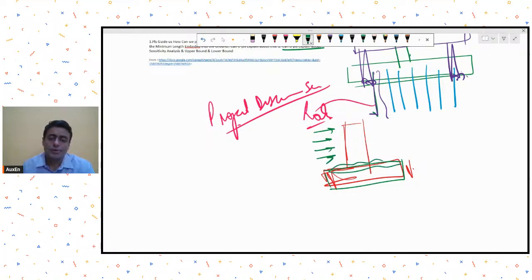So you basically want to see the podiums at two levels of stiffness. When I say podium, I also mean to add any existing basement walls and other podium slabs. Any system which is taking the lateral load due to wind and earthquake acting on this tall building and transferring it to ground, I am adding all of them in this podium system. So anything below podium which is there to resist the lateral load and transfer it to ground.